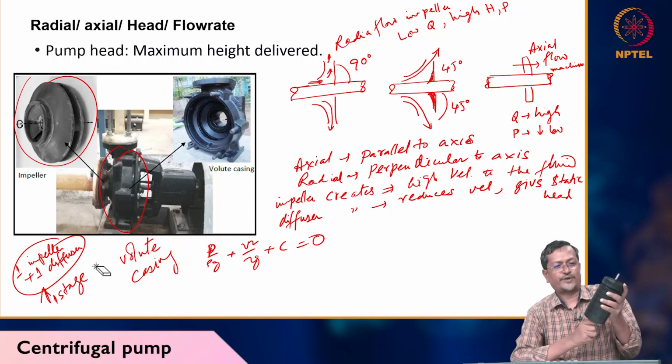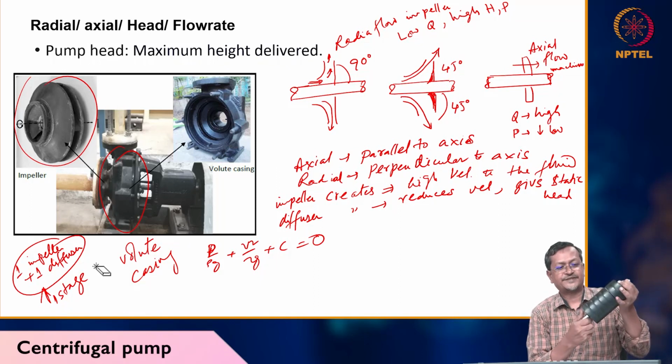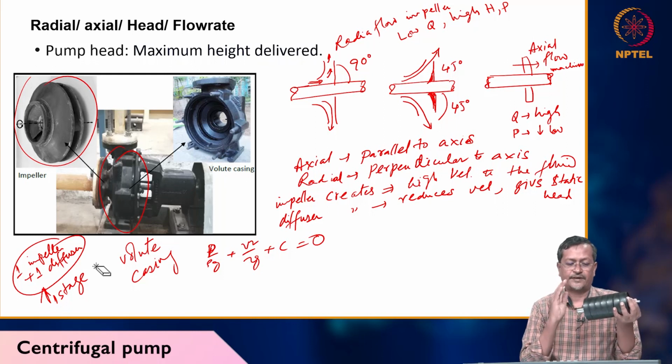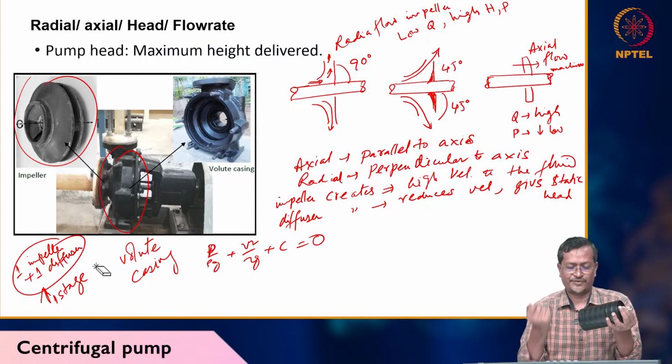Okay, an impeller rotating continuously. Take the 7 stages; if I assume each is 5 bar, it may not be 5 bar, I am just giving an example. If each one is 5 bar, then 7 stages means 7 times 5, so I am getting 35 bar pressure. But the flow rate is not changing.